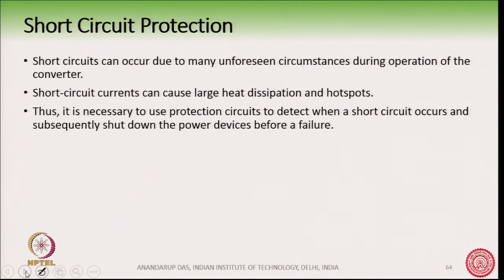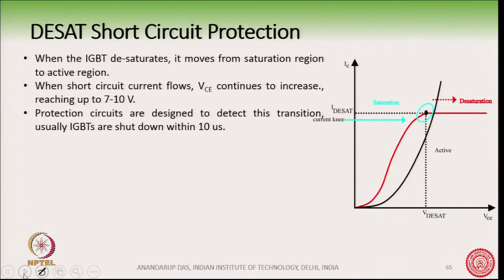So, the gate driver has the important job of withdrawing the pulse and shutting down the power device in a safe fashion before a catastrophic failure occurs. Basically, how does it do that? It monitors the collector emitter voltage.